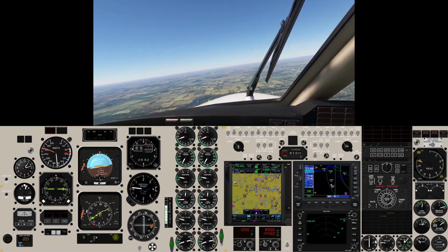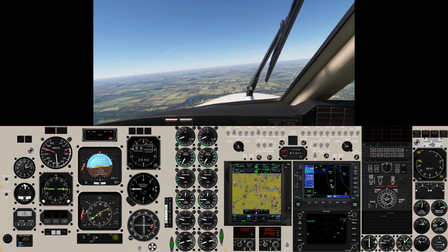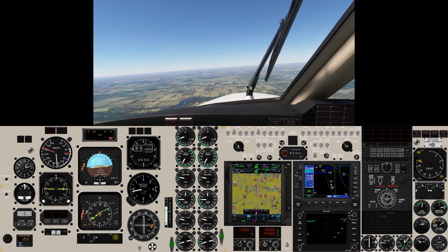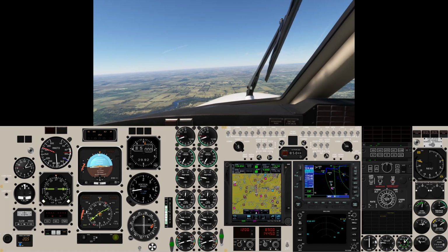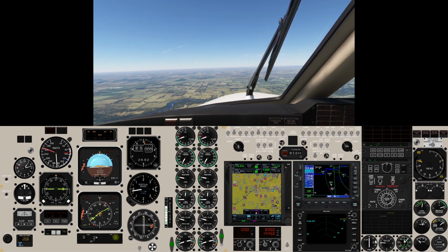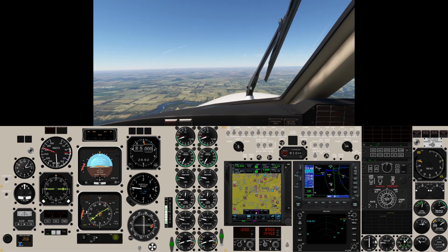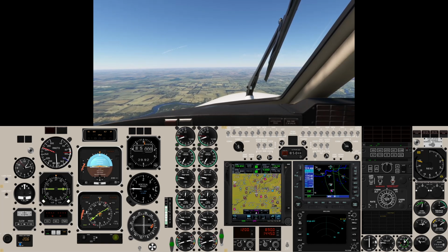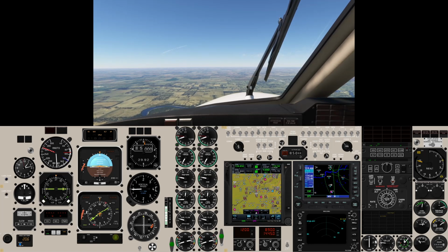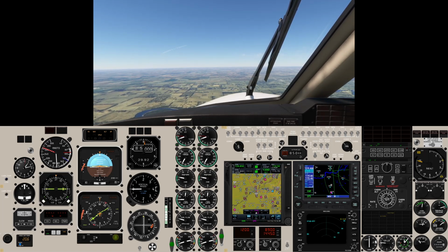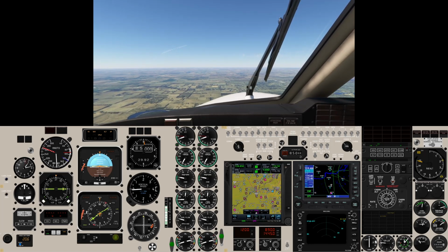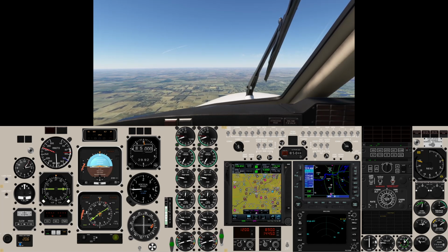Then the altimeter is fairly straightforward, probably one that you've seen before. It's got a nice rolling drum there with the altitude displayed and a single needle, just to give you the sense of the direction and speed of change. A VSI below that, again fairly standard stuff, and a CDI for your nav2 source. So that'll be the one that's tuned into whatever you've got as your nav2 source. In this case, it's the 530.